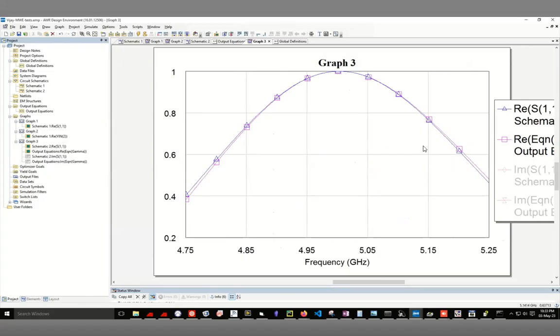And if you remember, the Q or the width, since we just discussed the width, delta omega, is basically given by 1 over RC, right? So if C becomes smaller by a factor of 10, R is still the same, it's 50 ohms, then the width is going to become bigger by a factor of 10, which is what you're seeing.